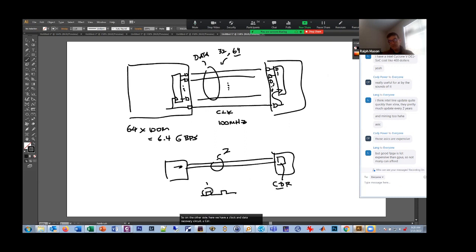And what it says is, oh, you know this signal here? There's some data values, like maybe this was a 1, and this was a 0, this was a 1. But there's enough transition so that it recovers the clock locally. So the clock and the data are embedded with each other. And when I do that, it turns out I can go much faster.